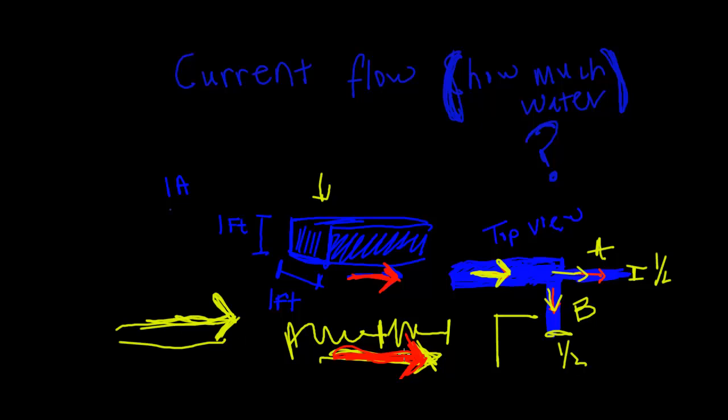All that matters is the water that you input in series is always going to flow through it over time. Like I said, the resistance of the water can restrict the amount of time it takes the water to go from point A to point B, and speed is a result of that, which is analogous to voltage. So there may be a voltage drop across the resistors, meaning the speed could be faster or slower. However, the same amount of water is going to flow through the channels in series.